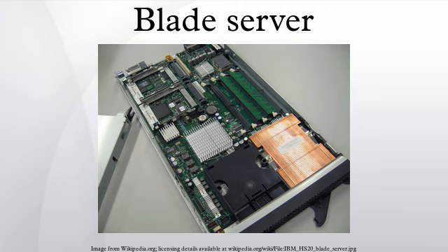PICMG expanded the CompactPCI specification with the use of standard Ethernet connectivity between boards across the backplane. The PICMG 2.16 CompactPCI packet switching backplane specification was adopted in September 2001. This provided the first open architecture for a multi-server chassis.